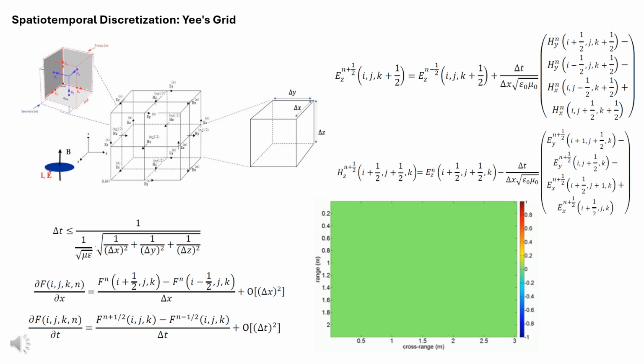It's important to note that reducing the mesh step size by a factor of 2 increases memory requirements by a factor of 8 and computation time by a factor of 16, highlighting the need to balance accuracy with computational resources. Note that accurate gridding is crucial for effective simulation. For uniform and straight geometries, Yee's grid is applied by discretizing them into rectangular cells. However, for non-uniform or curved geometries, this method may introduce errors due to misalignment.